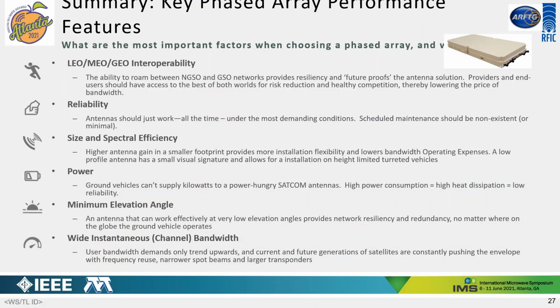In some cases, we may be embedding these antennas inside an aircraft or inside an enclosure, for example. That's happening right now. And in doing so, I already mentioned the thermal and the heat concerns, but reliability as well, because generally it's going to be very costly to have to replace these units or to service them after they've been enclosed. We talked about size and spectral efficiency. Generally, the higher the G/T, the higher the spectral efficiency, and the overall G/T efficiency is the key parameter for judging the size of an antenna for a given G/T requirement.